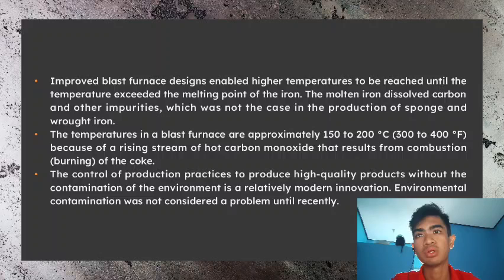The pig iron produced in a blast furnace has the advantage of being rapidly produced, but pig iron is very hard and brittle due to its high level of carbon. Wrought iron is ductile and tough but has little strength, while pig iron is strong but brittle and lacks the toughness to withstand sudden blows without breaking.